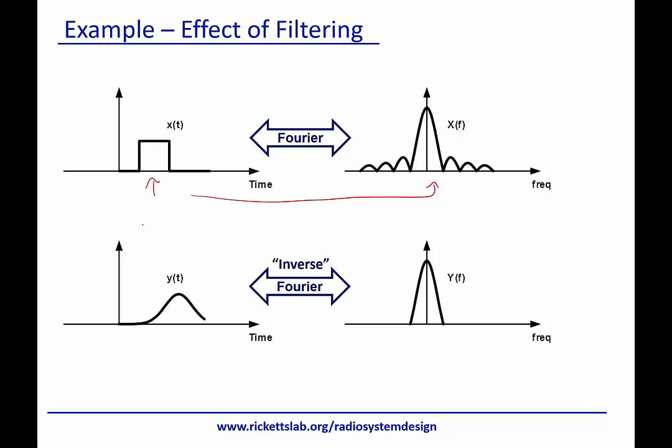If we were to take a low pass filter, and I'll draw that in the frequency domain, so imagine I put in a filter that has a pass band like this. It's pretty easy and intuitive from the frequency domain to realize we're just going to basically filter out all these sides, and this is the signal we get. But you need to remember that in the time domain it has an equivalent one, and it smooths it out.